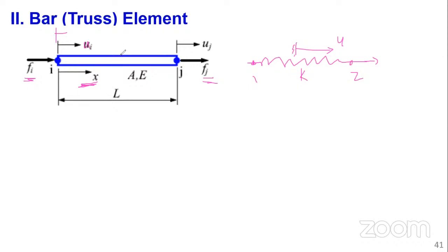Here, the rigidity or the stiffness of this member is now, because we are now dealing with a real structural member, we talk of the stiffness encompassing two things. One is the geometry, which in this case is described by the cross-sectional area, and two is the material characteristic, which is captured by the value E, Young's modulus.